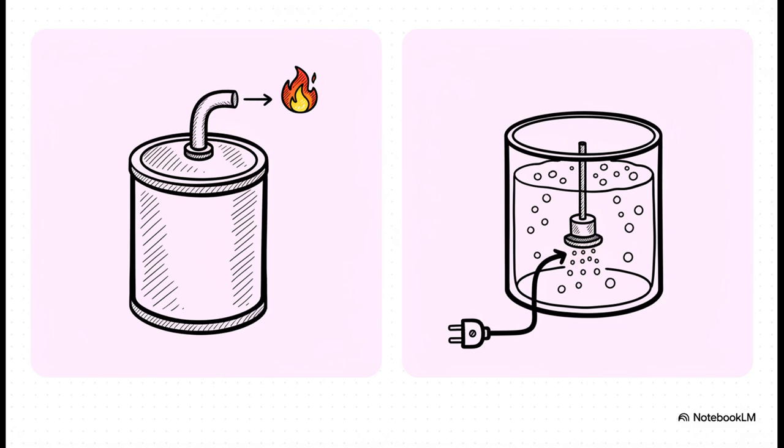We can use anaerobic digestion, which works without oxygen. It's a complex process, but it produces valuable biogas that can actually help power the plant. The downside is it's really sensitive. Or we can use aerobic digestion, which is way simpler and more stable, but it consumes a huge amount of energy and produces no methane. It's this critical trade-off between energy production and operational simplicity.